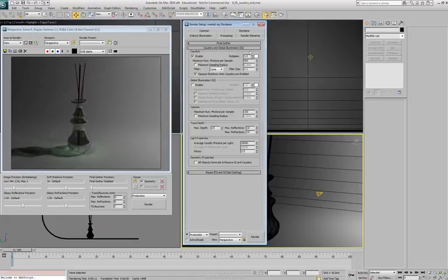Okay, now having looked at the caustic information, these are our basic settings that we're going to be working with. Our opaque shadows, when caustics are enabled, does just that. You can check that on or off. With it on, it is going to increase your rendering time by a little bit. Depends on your scene, depends on how it's used. We'll leave it on for the default. Those are good to go.